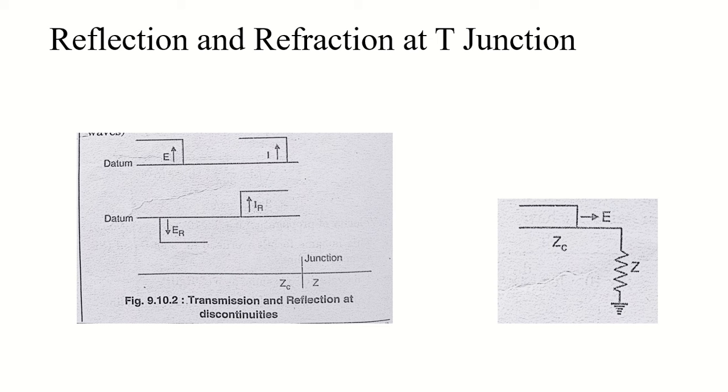So the line cable junctions and even the fault will constitute such discontinuities. And now independent waves will meet along the line and combine in accordance with the polarity to provide different voltage and current levels at the meeting point.